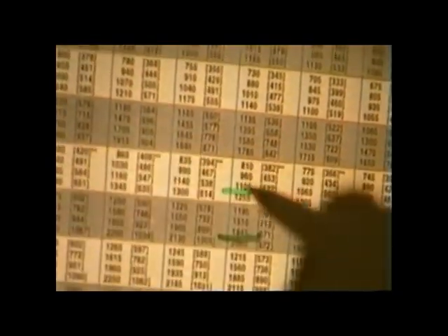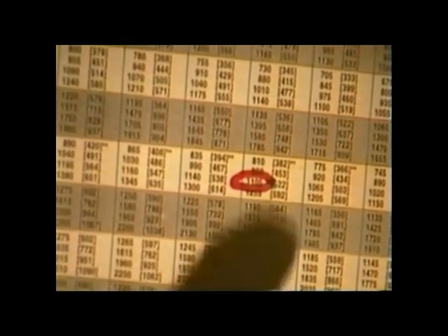Do you think, so we're looking for 1,200 CFMs, aren't we? Yes. Do you think this is okay? No. Well, it's a little light. It could be okay, but it's a little light though. But we could pick up a lot of latent heat. Could be a great dehumidifier. Yes. See?